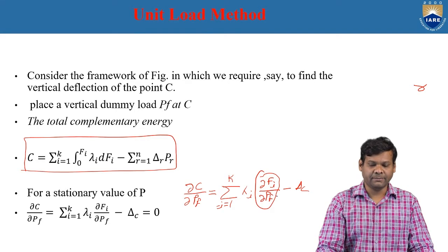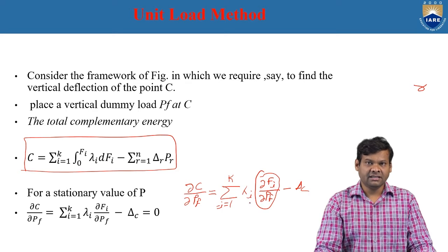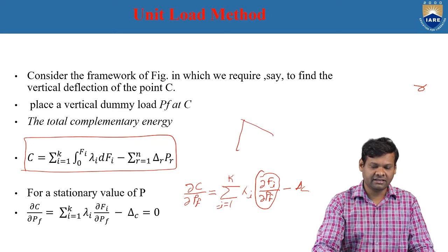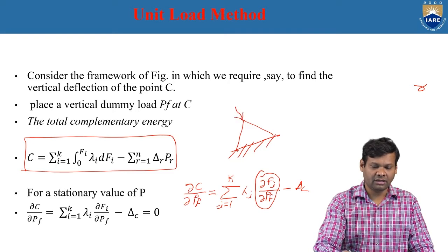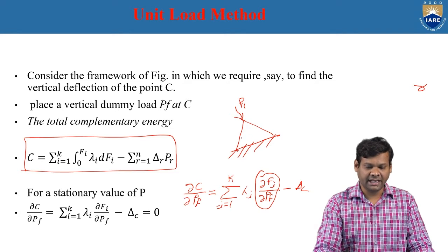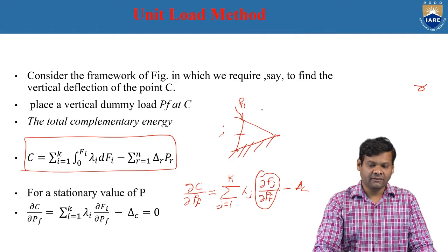Here, one of the most important terms is dou F_i by dou P_F. This is the change in force in an element with respect to a load. For example, when we take a structure like this and apply a load of, say, P1, we observe the load in an element i because of P1.